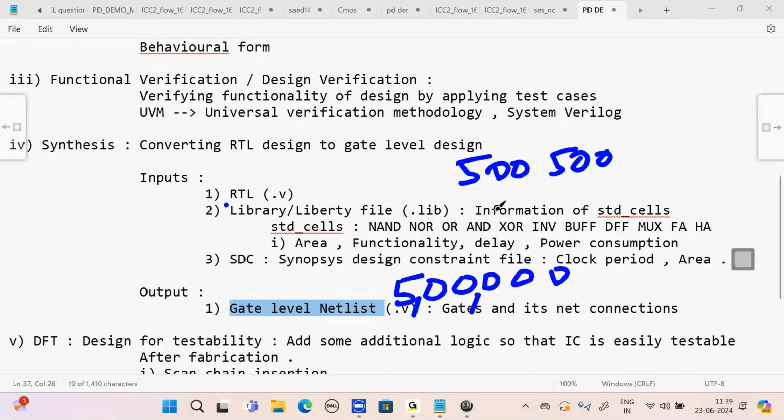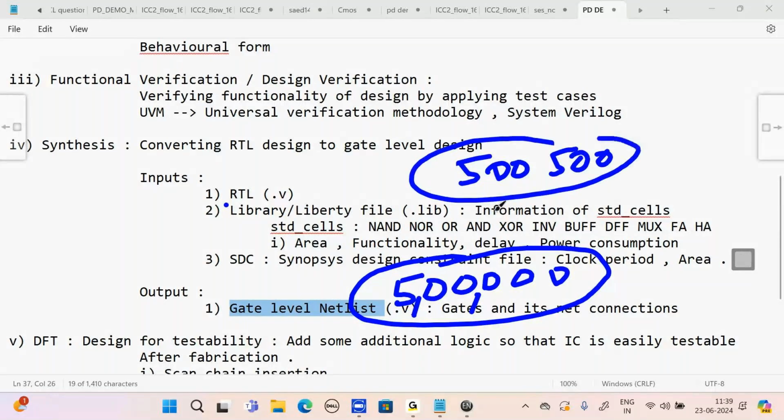No. Whatever the first release you have, take this first release and start doing your physical design. That may not be a proper design because the netlist is not completely ready. But still you can get an idea how your floor plan will be. What are the results you are getting from that? You can get an idea. It's like a practice match before the actual match.